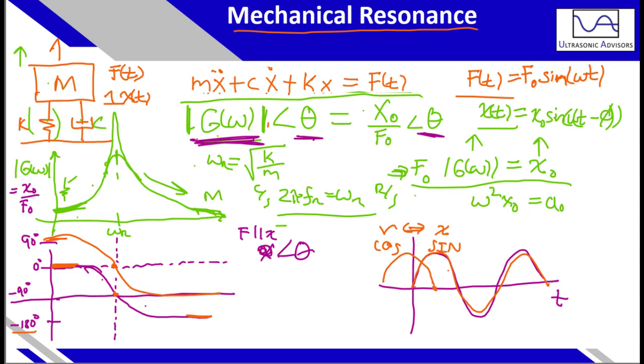So at lower frequencies, we have 90 degrees, which is kind of standard. At the resonant frequency, we're in phase with voltage, so the phase equals 0 degrees. And after the resonant frequency, the phase continues to decrease until you get to negative 90 degrees.